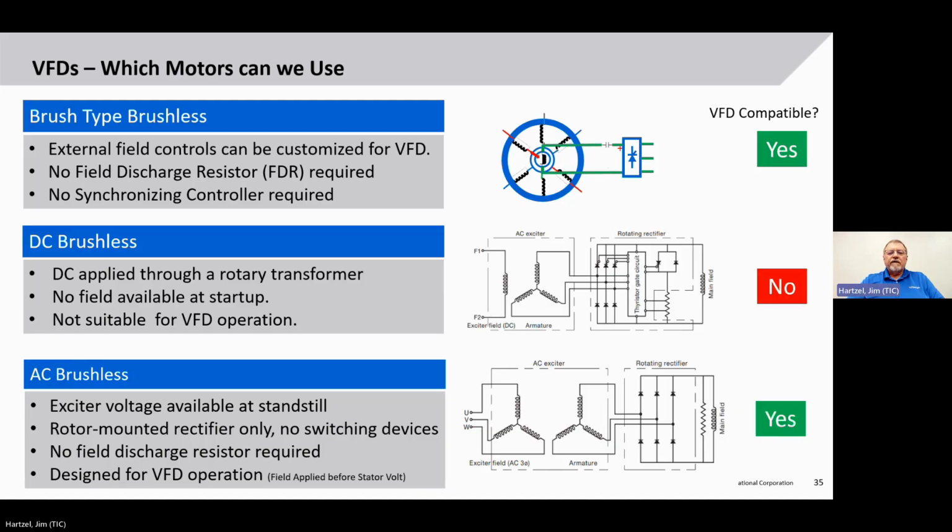So this is where it is very important in this section here. Remember the brush type motor, the first one we looked at? The external field controls could be customized for a VFD. So instead of having all that circuitry, we can just have a rectifier and a switch to apply the field directly.